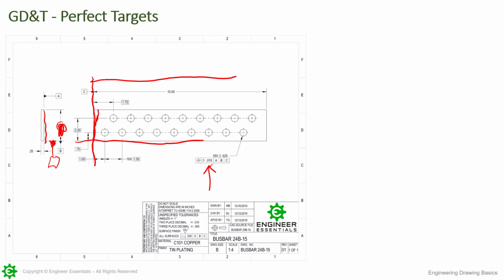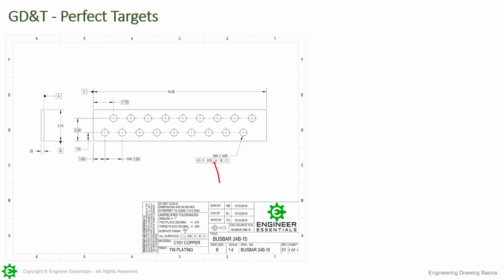So that's why there's zero tolerance stacks with position tolerance for the locations, because it's setting up the perfect datum reference frame, and all of your tolerance zones are perfectly oriented and located, and they're located with the basic dimensions from B and C, but they're perfectly oriented, perfectly located. They cannot move when we're at inspection. Nothing can alter those.